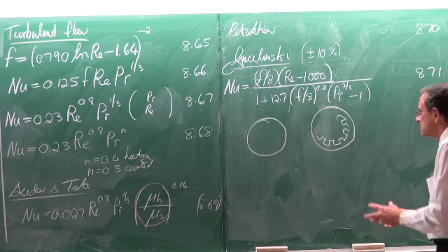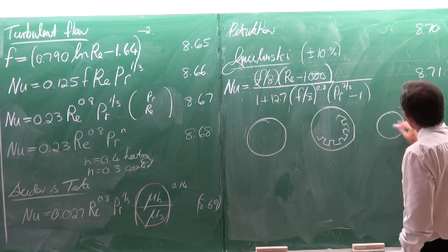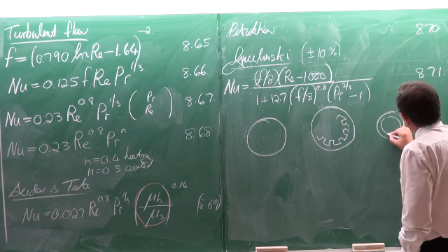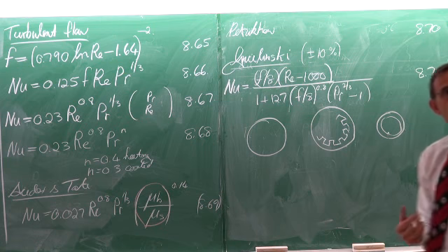And you will even have cases where some of the tubes that we have at the moment are typically about 10 millimeters in diameter, and then they've got very, very small fins, typically a height of about 0.3 millimeters. Very small, but they are also spiraled on the inside, like the inside of a gun barrel. So firstly there's more surface on the inside, but at the same time the bulk of the fluid is being rotated on the inside. And as you can imagine, that will also give you much more heat transfer.